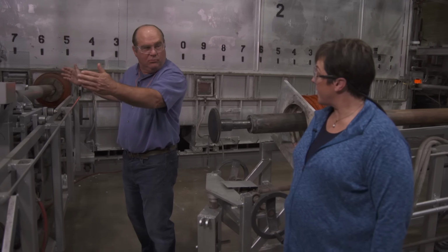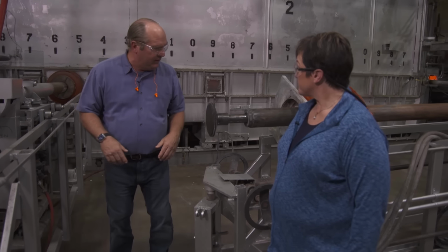And then we're able to start putting those top roll machines out on the very edges and stretch that to the width and thickness that we need. So you can stretch it like a taffy, pulling it to a sheet. Right. Each one of them pulls it a little bit more, so it becomes a narrow sheet. Does this leave a mark in the glass? Yes, it does. And then we cut that off and recycle it.